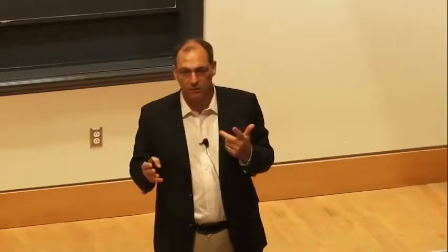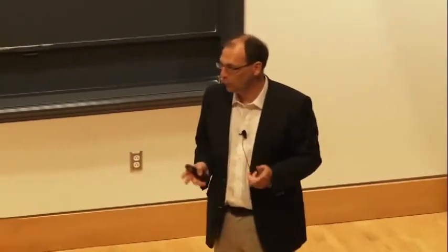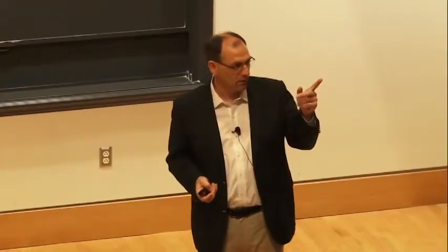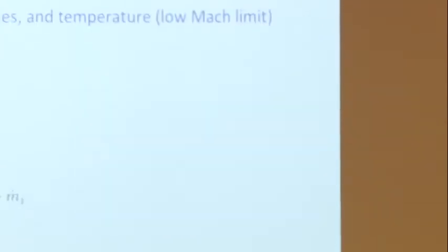So if you see in the literature, you see a lot of data for these premix flames, premix flat flames, for very low pressure. It's not because people are interested in low pressure, people are interested in high pressure. But at high pressure, the flame becomes so thin, you can't look inside, okay? So especially not with probe measurements. People often do probe measurements, and so, the probe has to be much, much smaller than the length scale you want to measure. If the flame is thin, the probe can't be small enough.